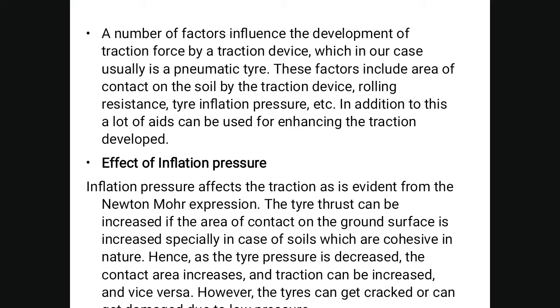Inflation pressure affects traction, as is evident from the Newton-Morse expression. The tire thrust can be increased if the area of contact on the ground surface is increased, especially in the case of soils which are cohesive in nature. Hence, as the tire pressure is decreased, the contact area increases and traction can be increased, and vice versa.